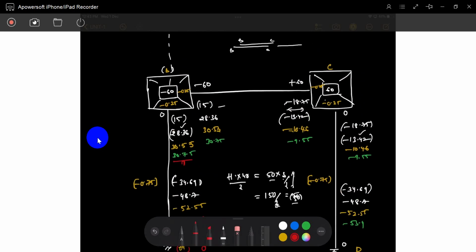MBA also take it. Its fixed end moment is 0. Its own rotational contribution is 30.75 multiplied by 2. For BA, the far end is A, so that is 0. The translational is 53.4. What will you get? It is 8.1. That is MBA.